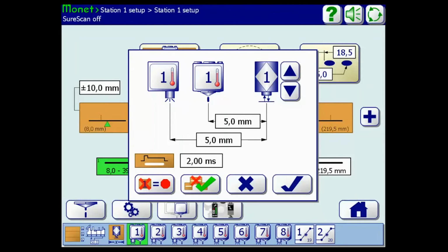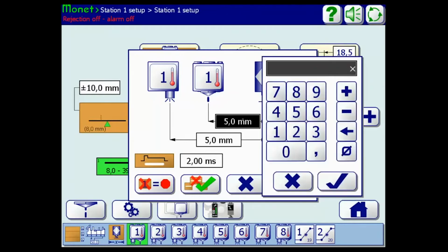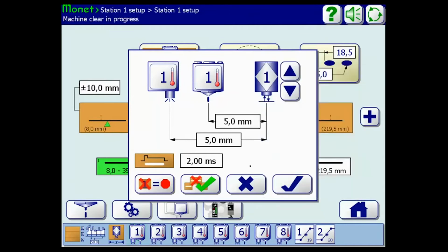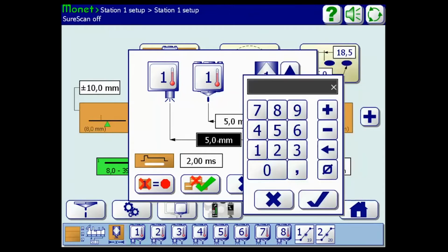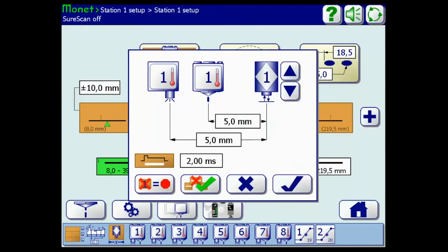The second measurement just below it here would be the same trigger light spot to the detection light spot, or the detection area of the hot melt detection sensor. So ideally, I would just plan to measure to the center of where that photo cell for the detection is mounted. Okay, so those are our two gluing and detection lead distances. First one, again, is a trigger to valve lead distance. And the second one is our trigger to detection lead distance. And again, we rely on both of those measurements to be as accurate as possible so the gluing and detection functions properly.